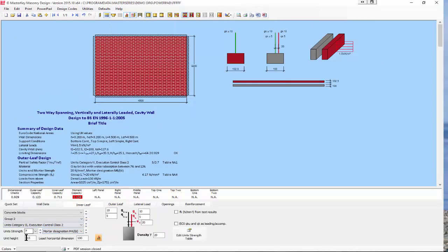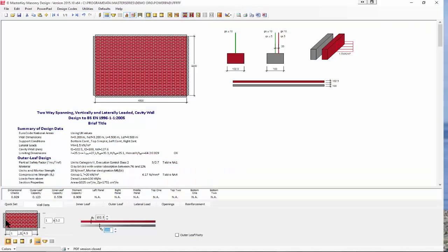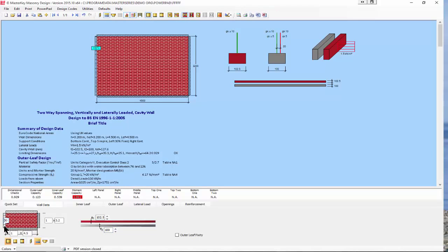well, let's strengthen our block, see what happens. It helps a wee bit. After a certain point, there's no additional enhancement to strength. So we'll leave it at the 10.4s. What we'll need to do is add in a thicker leaf or request that this is fixed. So quick set, fix it on that side, and it works. So if we could get fixity, it would work. We would be happy. If we could get 30% of fixity, it wouldn't work.